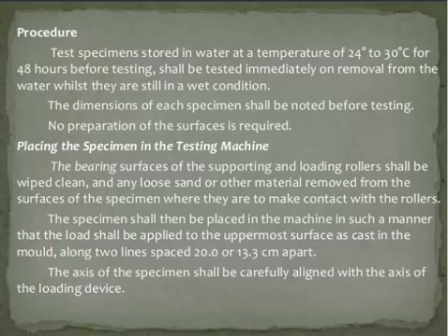And students, the procedure included in this flexural strength of concrete test. The important major point to keep in mind is that the test should be conducted on the specimen immediately after taking it out from the curing condition, so as to prevent surface drying, which declines flexural strength.